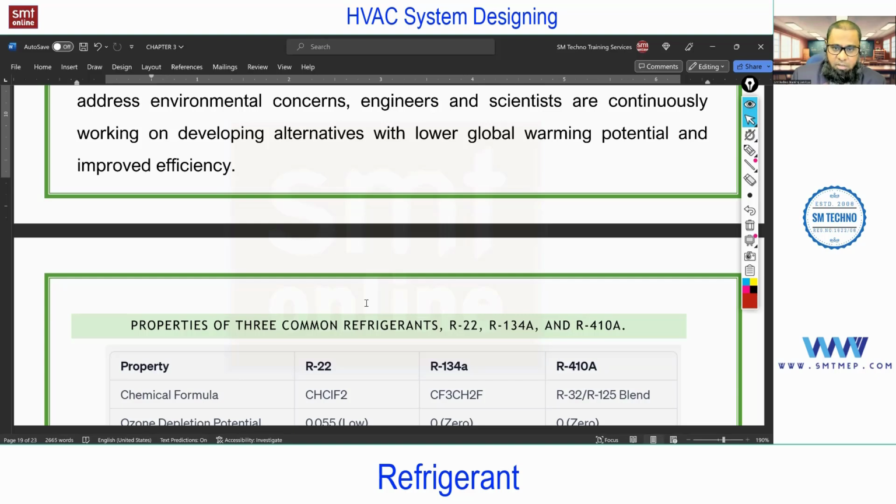But in VRF, we take a part, not completely, but partly. Even if you're not designing the VRF pipe, you must know this because you are responsible for verifying all this on site, even for testing and commissioning. Again, the testing and commissioning are also done by the manufacturer with their own software, because that is a somewhat precise system. Now, designing the chilled water piping, that is the water side, is the responsibility of an HVAC design engineer.